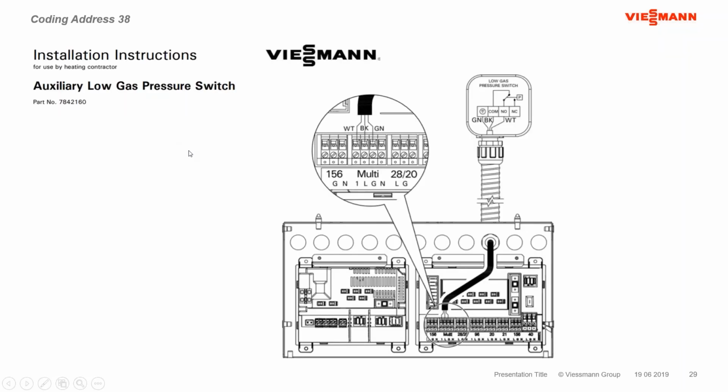So in our manuals, we'll detail things like auxiliary low gas pressure switches. Some jurisdictions, that little automatic reset low gas pressure switch on the gas valve on, say, the B2HA 399 and 530, because it's automatic reset, they want a manual reset switch on there. They might require you to put that manual reset low gas pressure switch. You might have an application with a high gas pressure switch that's manual reset. You might have a temperature limit that opens and needs a manual reset on it.